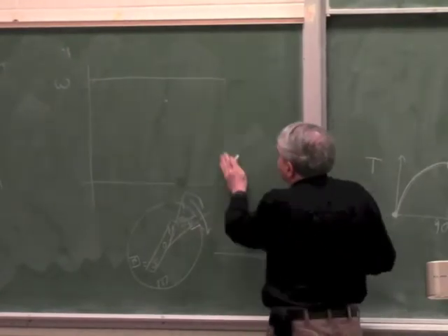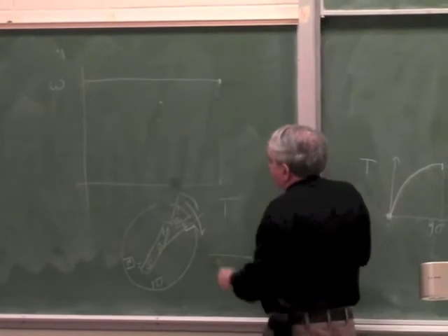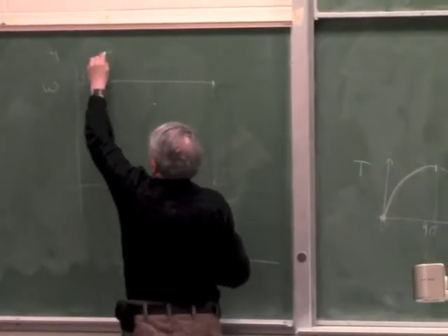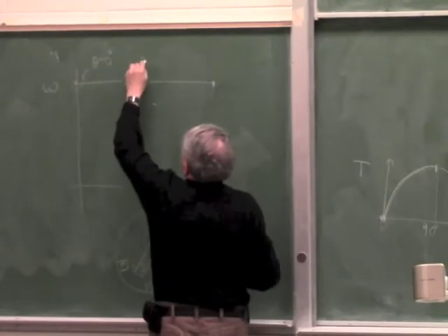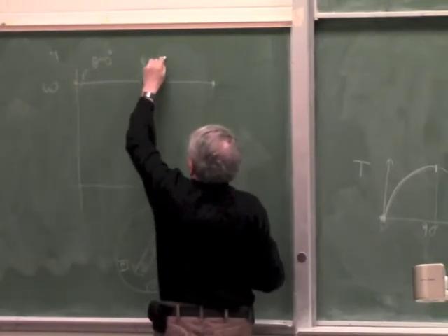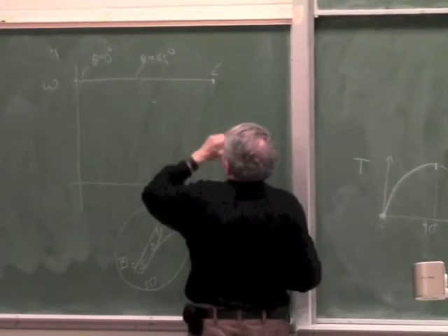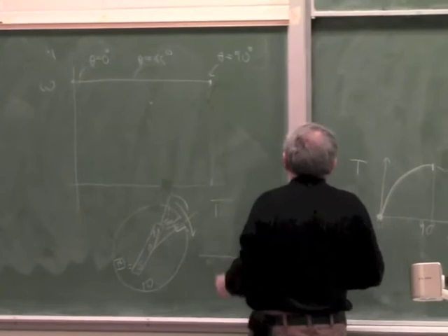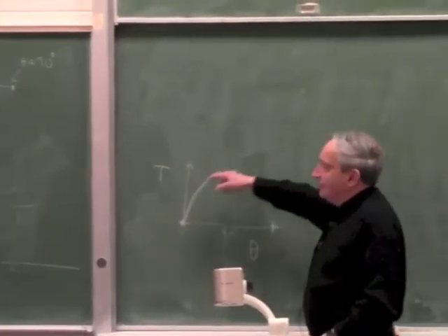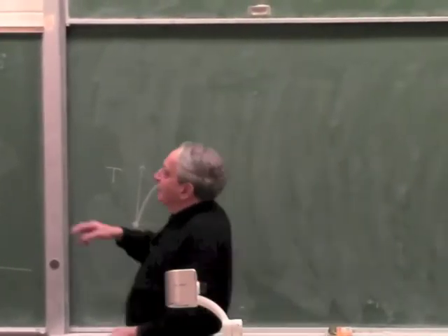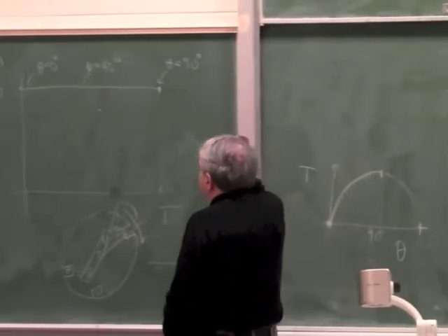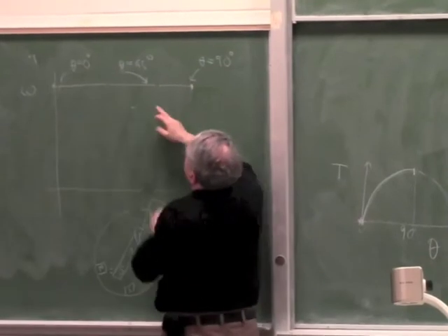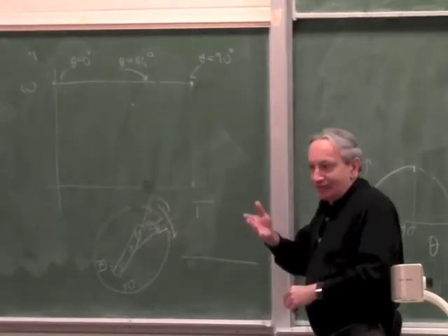What happens, it collapses. If you reach this point, so this power angle here, theta is 0, because there's no torque. Let's say here theta is, say, 45, and let's say here theta is 90. I mentioned to you before that it's actually a half sine. So at 45 degrees you have 0.7 of the torque. So it'd be more accurate to draw theta 45 as this point, because sine 45.